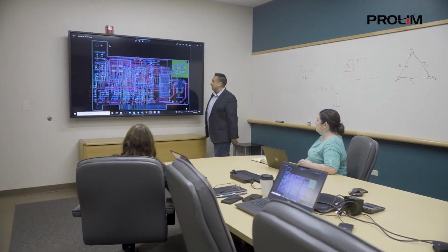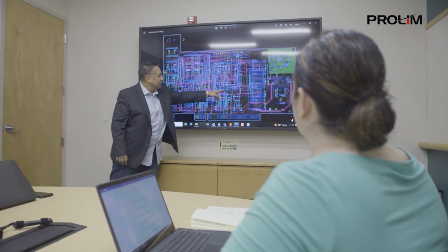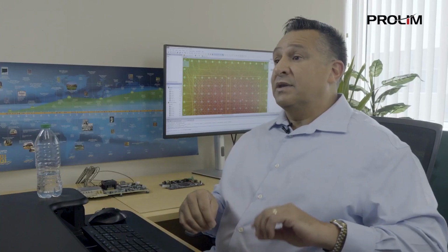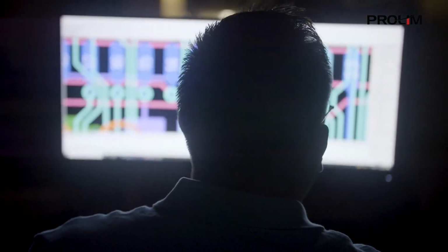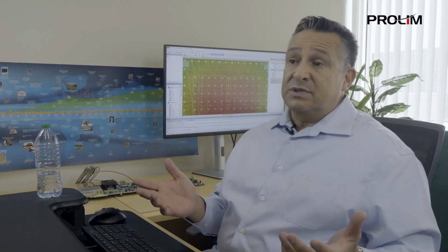When we think about what kind of value they bring, you have a more efficient way to design complex systems. You have a way of optimizing signal flow from board-to-board connection, a way of eliminating connectors, and the ability to implement complex requirements into your design. When you talk about high pin count BGAs and so forth, especially as the pin pitch gets tighter and tighter, sometimes you have no choice.